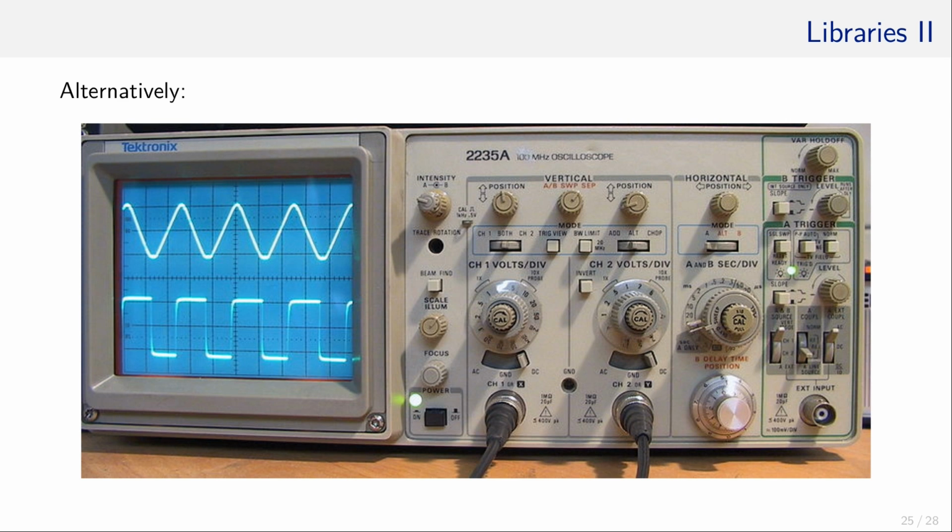If the software implementation does not work, an oscilloscope is a powerful tool to track down any timing violations. Make sure that the sample rate of the oscilloscope is at least double, better 4 times the frequency of the signal to be sampled. As a rule, a more sensitive oscilloscope is always better. However, they become costly very fast. Usually, the small ones start at around 150 to 200 US dollars with no upper limit.